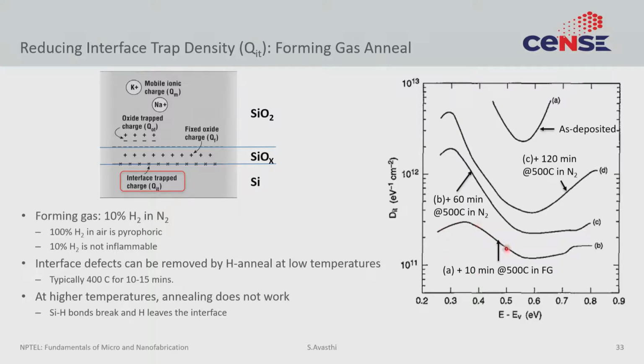If you take the same curve, the same wafer, and now turn the forming gas off and introduce nitrogen, which is inert, you would actually make the situation worse. The hydrogen from the forming gas would come off, desorb from the interface, and as it desorbs, it would make the silicon dioxide interface a little worse. The defect density will actually increase. And the longer you keep the wafer in this nitrogen atmosphere, the worse it will become. So it became very good, which is curve B, and then it becomes a little worse, and then worse and worse, all the way back to where it started.